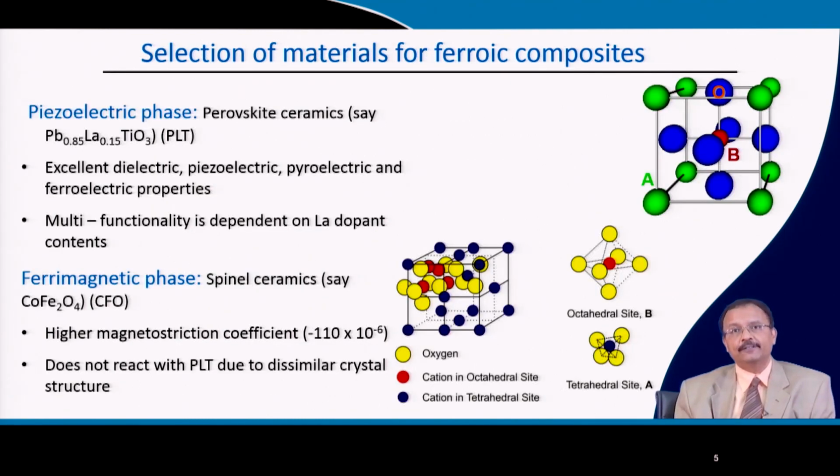So, one example can be given that is ferroelectric in nature. You know that ABO3 type of material, particularly lead titanate, is a well known ferroelectric material, and it is doped with lanthanum. So, lanthanum is in +3 valence state, which is replacing mostly +2 lead, but it has a probability to go to titania side also. So, from your defect chemistry, you can understand that lanthanum can act as a donor dopant if it replaces lead, and it can also act as an acceptor dopant if it replaces 4 valent titanium.